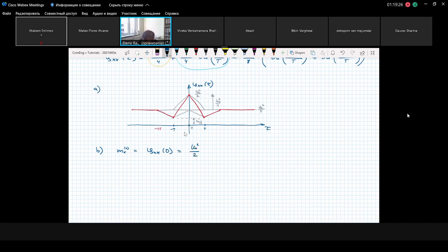On the other side, if we want to calculate the first moment, we can notice that if we take a delay large enough, so that the two sequences will be uncorrelated, the point at the limit when the delay is very large corresponds to the squared value of the first moment. So the first moment squared is nothing else than the limit when tau goes to infinity of our autocorrelation function.